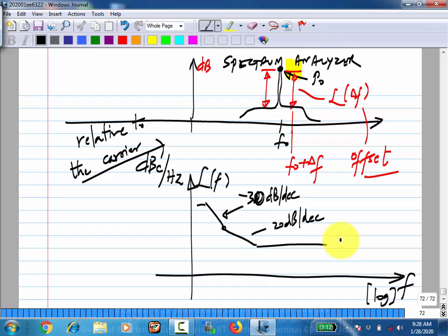If you look at any clock generator or an oscillator, you will be given the phase noise spectrum. And once you have the phase noise spectrum, you can calculate the time jitter, or phase jitter, or unit interval jitter. They're all scaled versions of each other. Only thing you have to remember is that this L of f is one side of the two-sided spectral density, so you have to multiply it by 2 before integrating. There are some problems in the tutorial which relate to this.